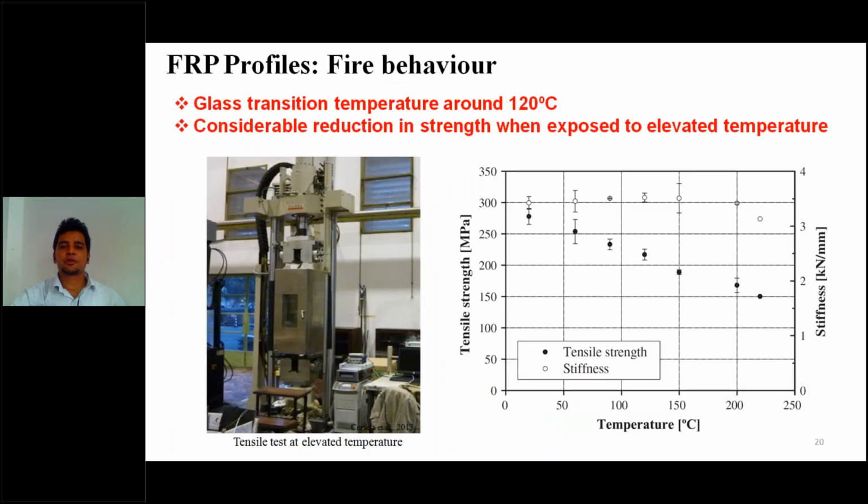Coming to fire behavior. Fire behavior is a major concern for structural engineers, because the glass transition temperature is around 120 degrees centigrade for GFRPs.